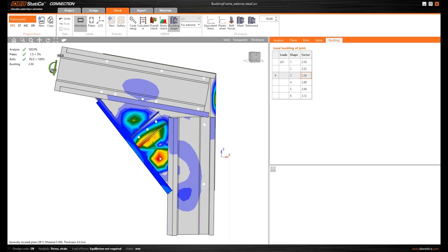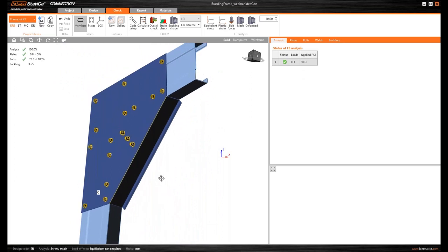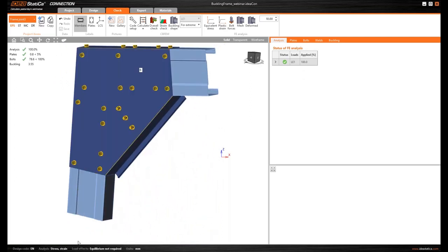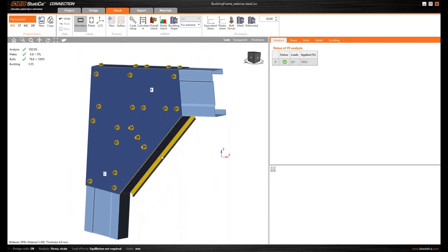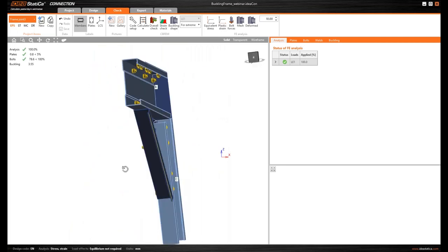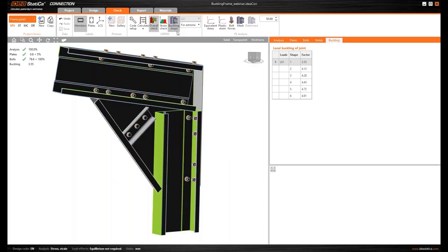it's a never-ending process. So for me right now, the best way is to increase the thickness of the plate. So I prepared that in advance. And next step, you can see that this whole plate now has the thickness 4 millimeters right here at the bottom, and the other plates too, because in reality it will be a bent plate. And what about the results? Let's check it out. Let's go to buckling and buckling shape.